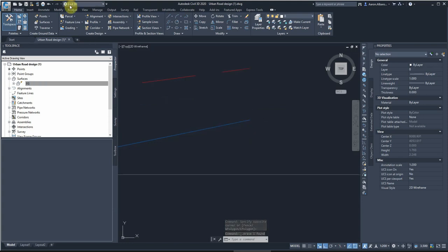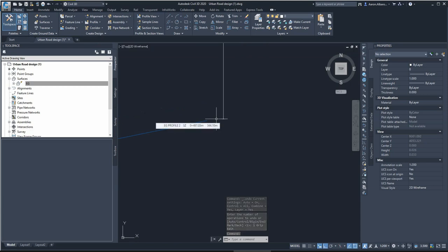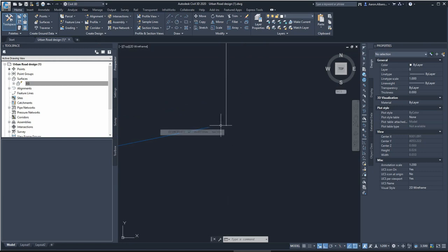What I had before, let me undo so I can understand why the issue is created. What I had here, I've got an area of the alignment that does exist, that space here, whatever it is, could be a very small space. It doesn't have any information about the profile. It has a gap here, so it can't read any information on the profile, and that will create that huge drop at the beginning or the end of your profile.